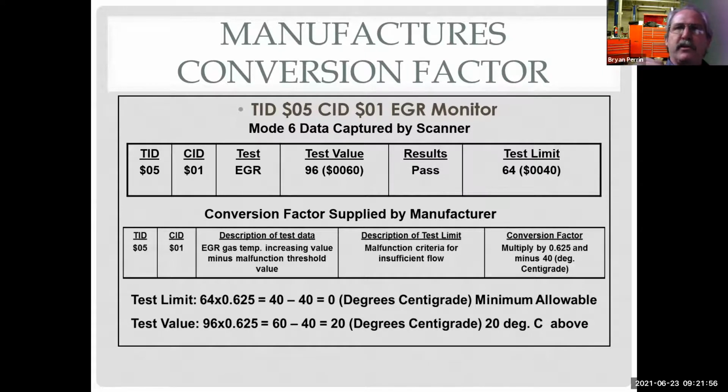So this is what I was talking about by we're measuring for degraded components. If I was looking for something that's bad, it would be a 0 degree increase, right? That's broken. That's the kind of thing that we would set a code for with OBD1 or pre-OBD2, is it working or is it broken? Now with OBD2, we're really looking at degrees of good. Because a 40 degrees centigrade change is still a huge temperature change. So the engineers probably figured out that at a 40 degree Celsius change, we're still probably going to be able to manage our emissions with the catalytic converter and other things.